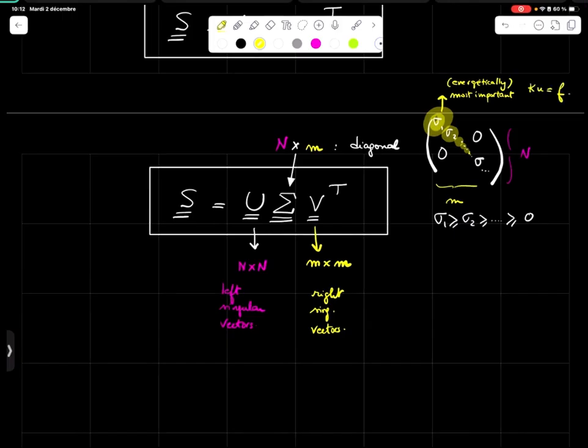For example, Ku equals F is not necessarily stiffness times displacement equals force, because you can solve that for any type of problem you're interested in. But usually this is the notation people use, because K is the spring stiffness, U is the displacement of that mass, and F is the force you apply on that mass in order to displace it. That's typically the way people talk, but it doesn't mean it's only applicable to mechanics. I think I convinced you of that, because we talked mainly about other problems, but I just want to make that clear. So energetically is again a physics-based interpretation.